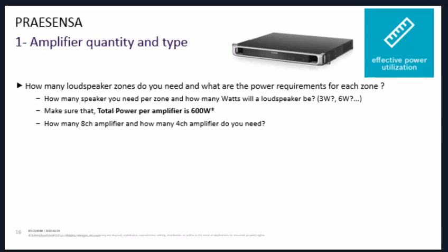Here in PRAESENSA, it's much more flexible. As there's a smart power sharing, you don't have to take care individually of the loudspeaker zones. The only thing you have to make sure is that total power per amplifier is below or is equal to 600 watts.